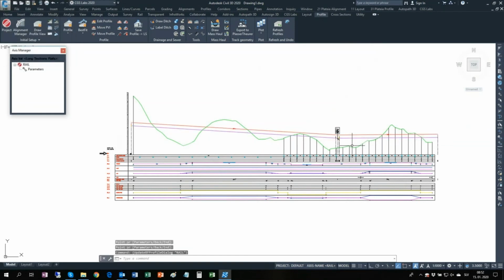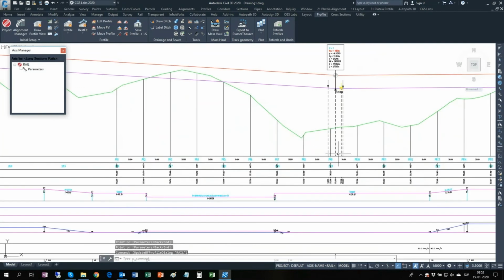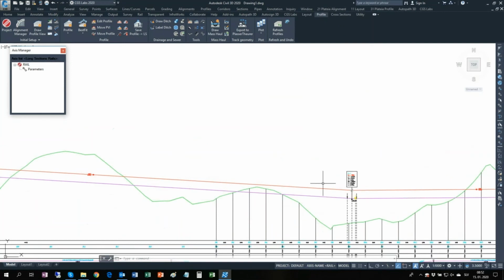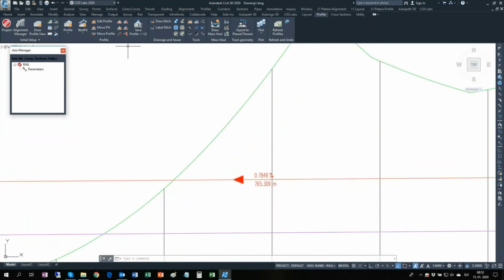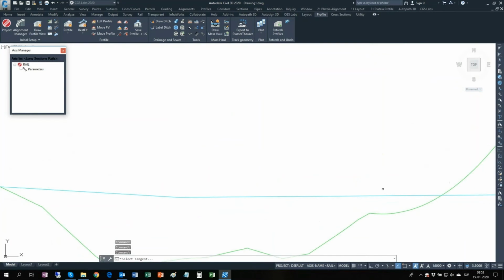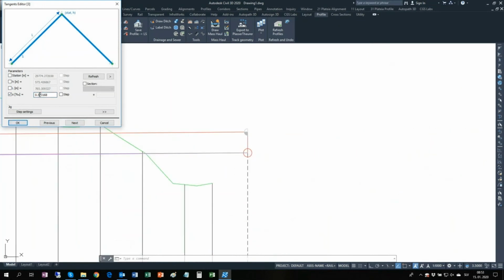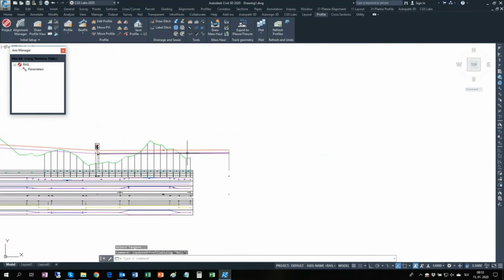We insert it basically just by entering the PVI location, but then we can, to a very high level of detail, set all those parameters according to our needs, defining the station and height of that PVI, what the slope of the profile should be, and everything else we need to be really accurate in this part of our design.